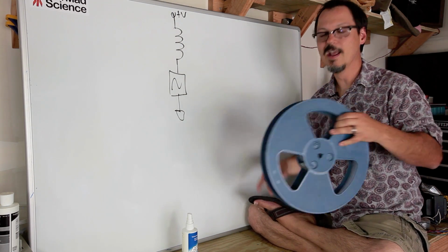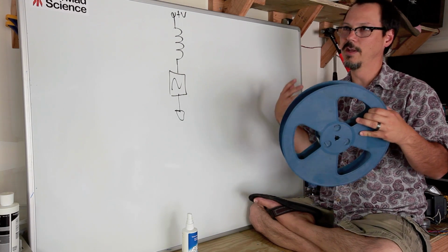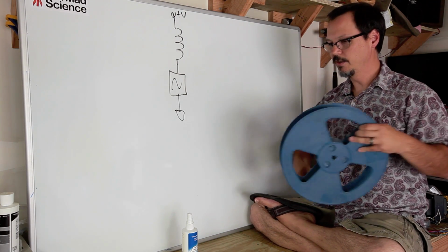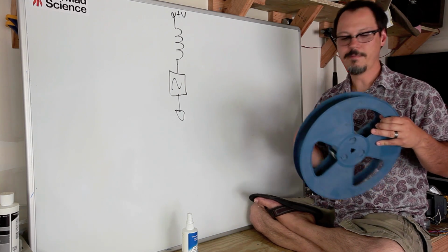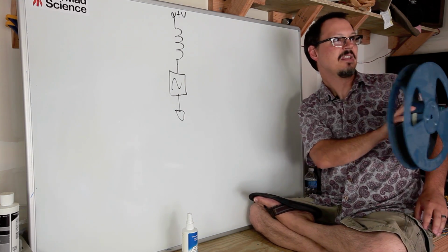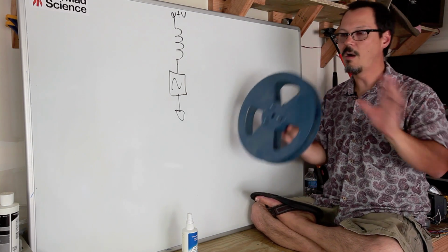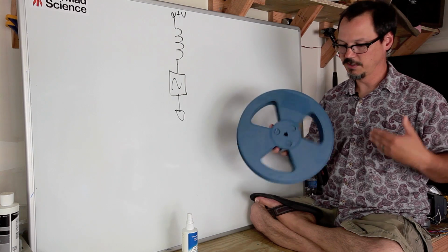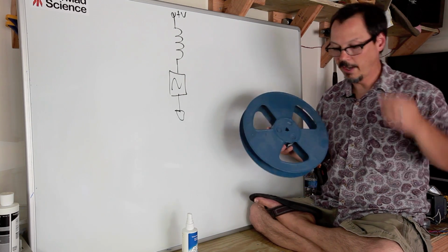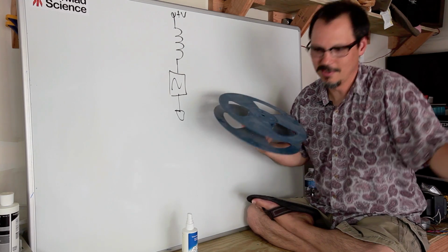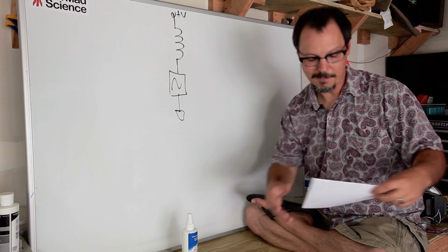I'm going to get to that in a second. I tuned it with a cap for like audio range, like 1000 hertz or so, hooked it up to an op amp and some headphones, and suddenly I've got a pickup coil where I can hear people's TVs and stereos and all kinds of electric junk that happens at audio frequencies because it turns into this giant pickup coil. Okay, that's another thing you can do. Now that's not a standard application, that's just some junk I made up, but kind of fun nonetheless.